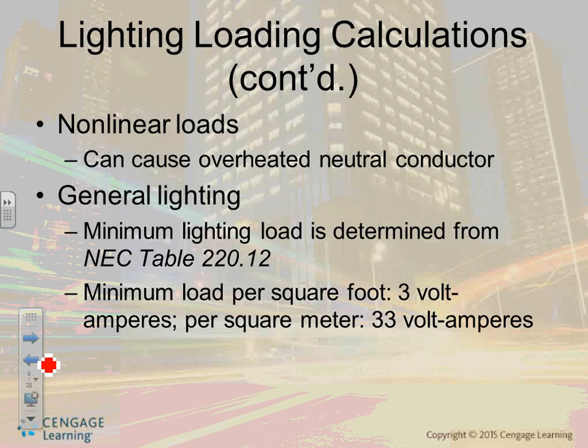That's why they call them energy efficient ballast, electronic ballast. So they chop the frequency. They're not running them at 60 hertz. They run them at thousands of hertz. The arc. Remember, this is an arc. They're arcing to create the arc and maintain the arc. So yeah, you need a driver to get you the DC for LEDs. You need a ballast to get you an efficient fixture and to maintain and run it efficiently. If that makes sense.